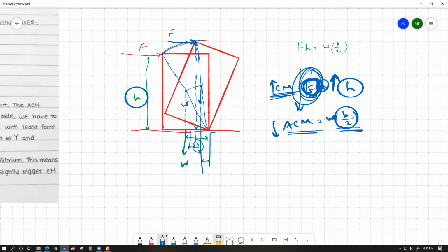Gotcha. Why did we use the term minimum force at the beginning? The reason we use the term minimum force is because in this whole process for the object to be toppled over, we have to keep applying this force F from this point all the way until the object actually becomes perfectly vertical. For example, when the object becomes right at this orientation. So when this is perfectly above this point, this is the point. Beyond this point, the object is going to fall down. Not a perfect drawing, but you do understand.